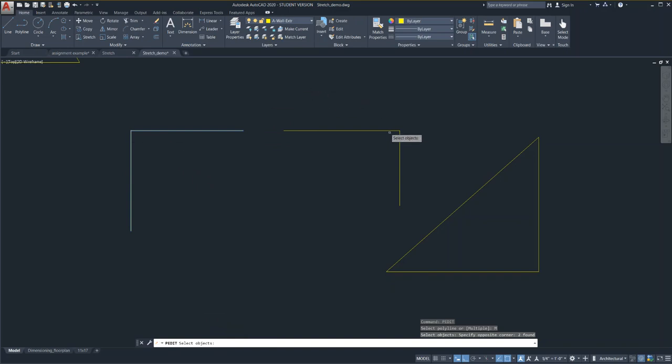So if I selected these two lines they would join together, these two lines would join together, but they would not connect to one another. Okay, lines that you use polyline edit on have to be connected, they have to touch. Okay, so p-edit, enter, M for multiple, enter, select your objects. I've selected both of my objects, I hit enter. Convert your lines to polylines. Click on yes or hit enter.